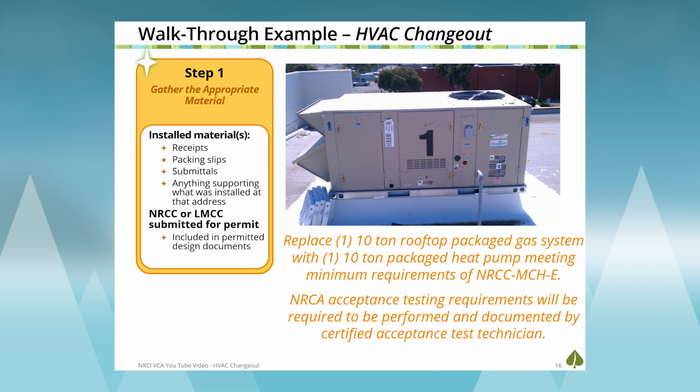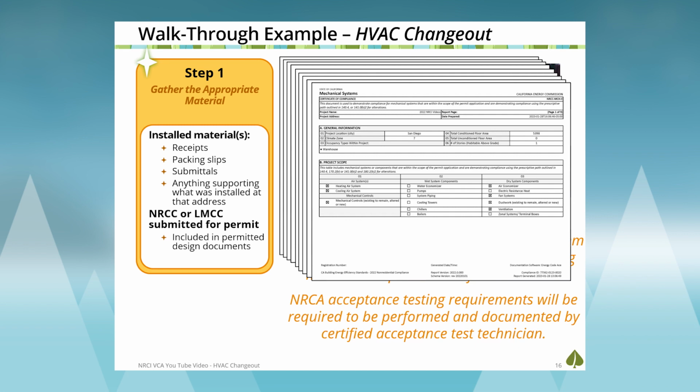Both the certificate of compliance form, the LMCC or the NRCC, and the certificate of installation form will help you and provide guidance on what pieces of equipment need to be tested and what that testing protocol is. We may also have HERS measures that have to be confirmed and tested by a HERS rater, such as that duct testing. Again, the certificate of compliance form will tell us when that's needed, and also the certificate of installation will support what additional testing may be needed.